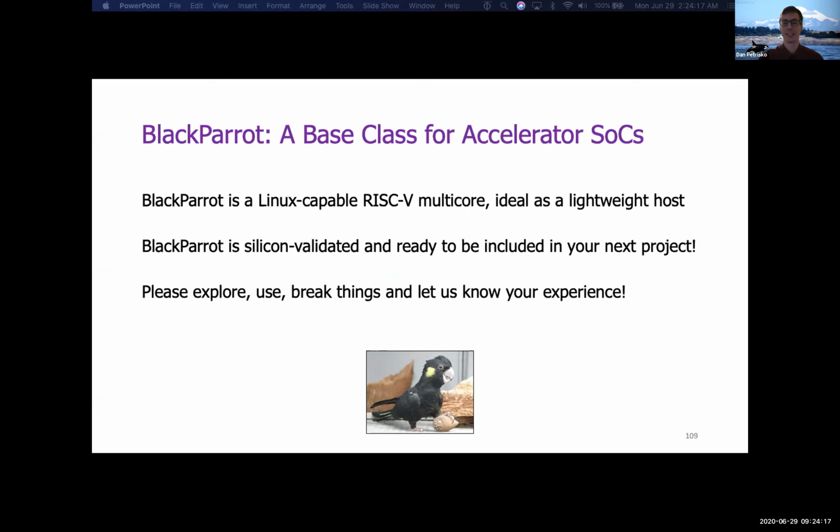The second reason is that between the memory IO network and Bedrock network, there are different constraints and different optimizations you can make. For example, in the BlackParrot chip that we taped out, our memory network was only a 1D network because it only had to go down to where the DRAM controller was on the chip. So you can save on an entire direction and routing for that. So it's good to have this kind of orthogonality, but you could certainly combine them in your own physical implementation.